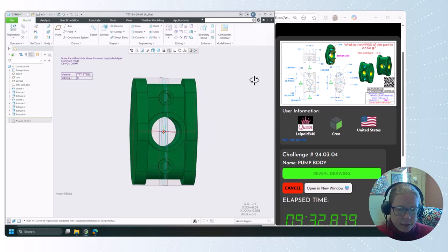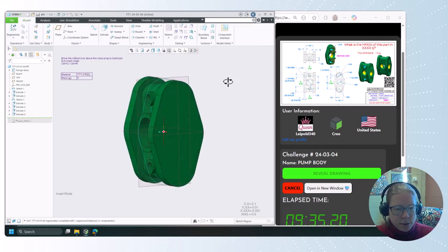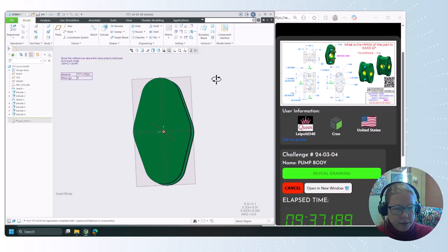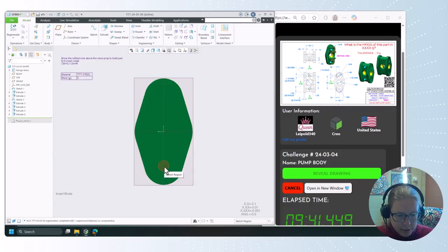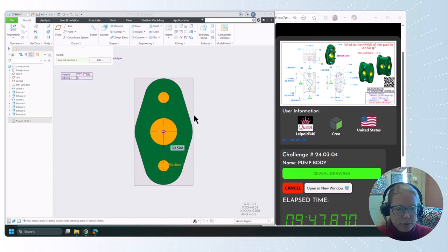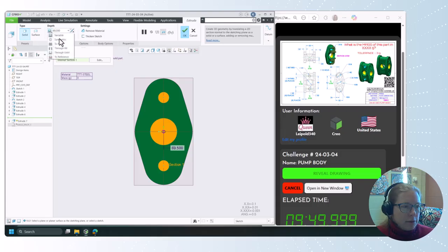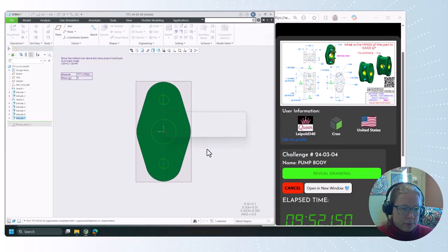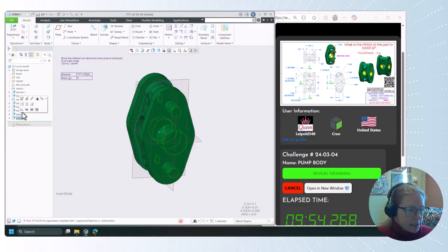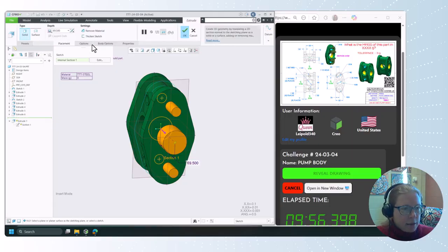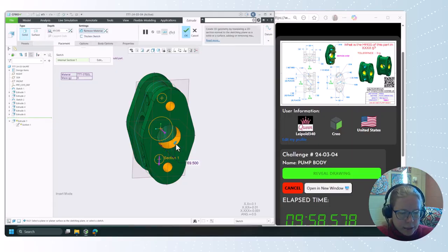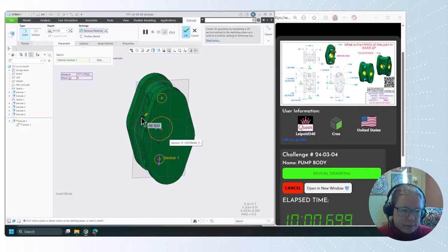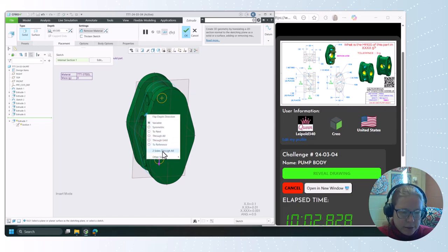All right. Now we're all set to jump in from the right side view. Let's pick this one and this one and this one. Extrude those. Those are going to go, oh, let's edit definition on that thing. Removing material, and again, right click on the drag handle. Does that way too often to me. Two-side through all.